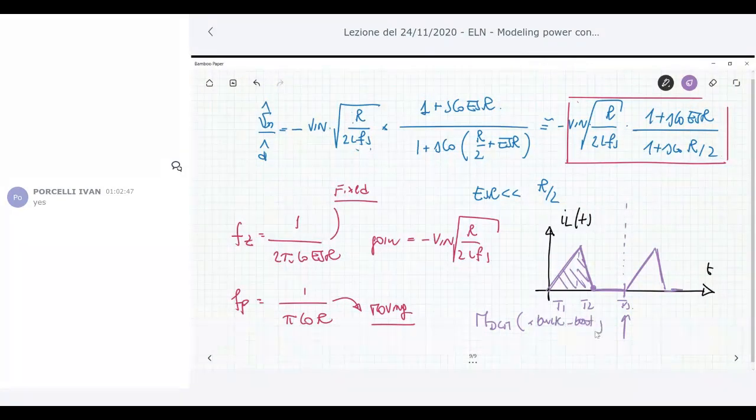Okay, and that consideration said that all the energy that is stored is released in the same interval. This happened the same. Okay, there is another way: no memory, cycle by cycle, of what happens in the previous cycle. Okay, this does not happen in CCM. In CCM, the inductor, which is storing the energy, is not completely released by the inductor in the same cycle.